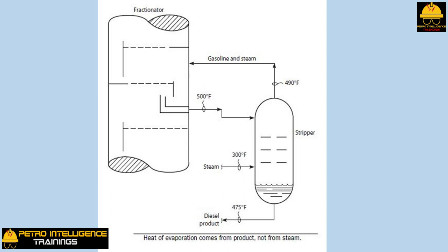I was once working in a refinery that could not meet the flash point specification for its diesel product. Flash point is the temperature at which a hydrocarbon will ignite when exposed to an open flame. To raise the flash point of diesel oil, it is steam stripped to remove the lighter, more combustible components. I noticed that I could drain water from the bottom of the steam supply line to the diesel oil stripper. I then screwed a steam trap onto the 0.75-inch drain valve on the steam supply line.